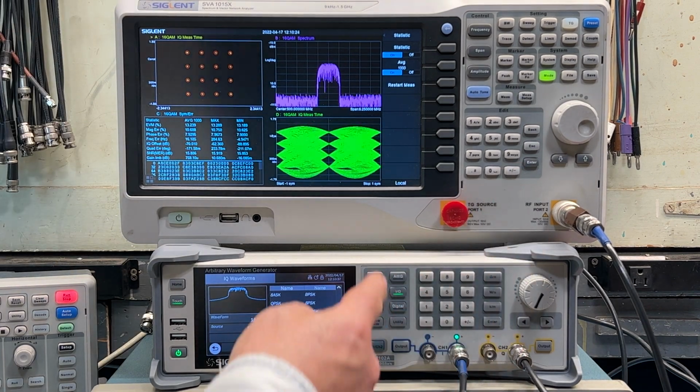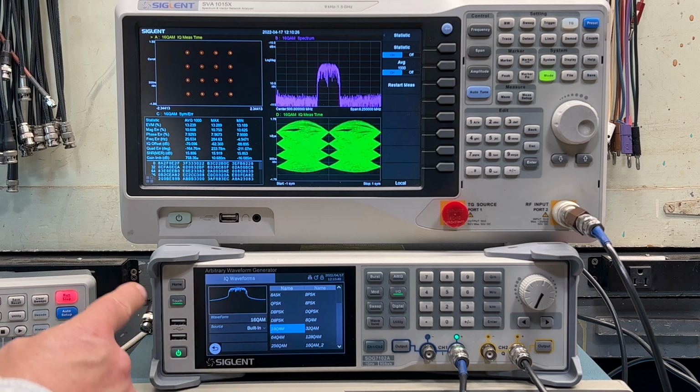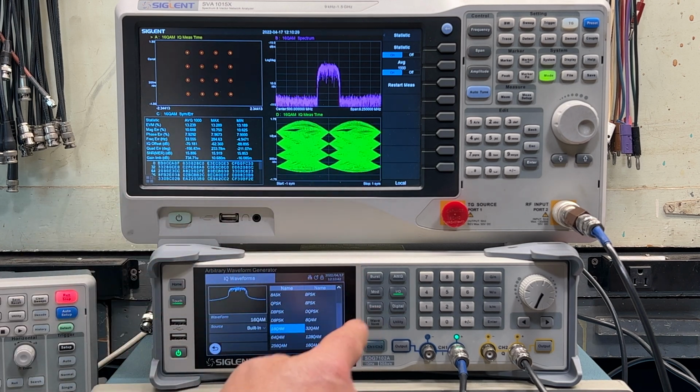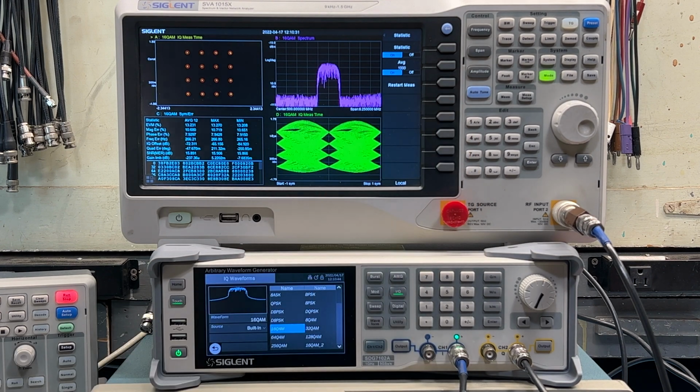Now, you can see once I've disconnected the clock from this to this, this waveform jumping around. Let's restart the measurement. And so at 500 megahertz, the clock in my spectrum analyzer is 266 hertz off from that in the waveform generator. Which one is right? Without a standard, I can't say for sure, but I'm going to bet it's the waveform generator with its ovenized oscillator.